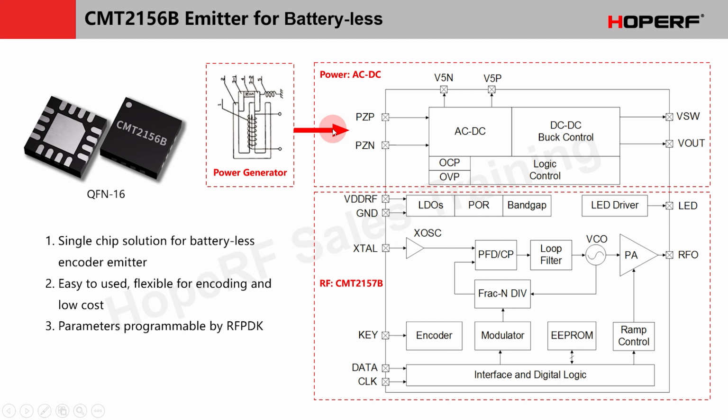To transmit, it's an alternating current, and it's a one-time, short-duration AC energy. The chip needs a small power conditioner inside. We need to input AC power to convert it into DC, and then through efficient DC-DC voltage regulation to power the chip's internals. So its special feature is an additional power management module.